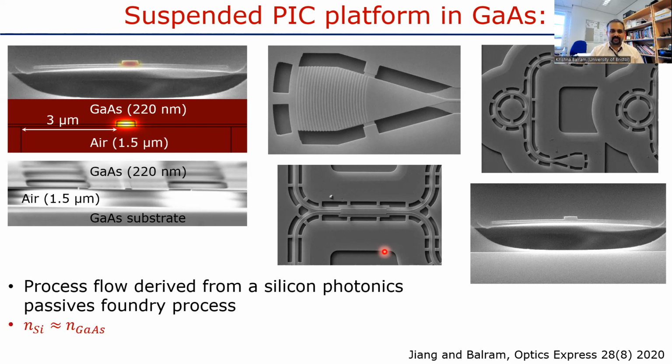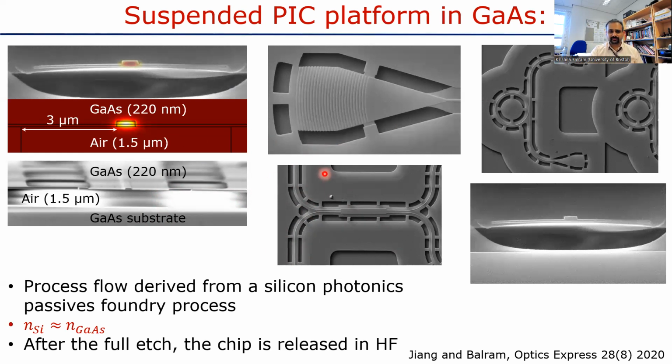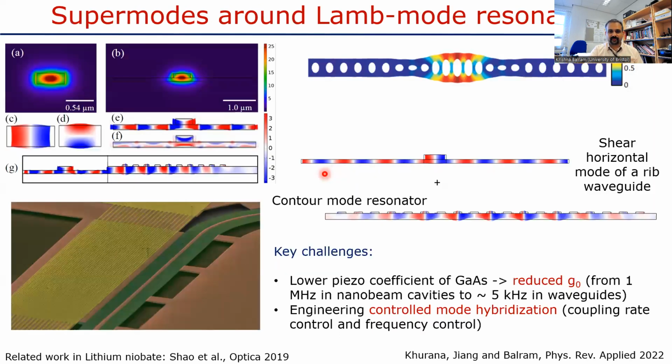So this photonics process is basically derived from a standard silicon photonics process, except that now we have everything suspended. The waveguides are suspended, the grating couplers are suspended. And the suspension allows you a natural route towards getting the MEMS inside this process.